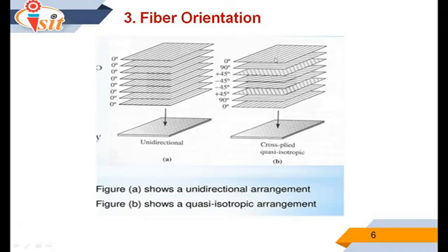In the second picture, at the right side, you can see that in the first plate the fiber angle is at 0-degree. But in the second plate, the fiber angle is changed to 90-degree. Then in the third plate, again it is at 45-degree. In the fourth plate, it is 45, but in the reverse direction. That's why we have written plus minus 45 here. And in the next plate, it is the same, and we have made a symmetrical impression at the bottom side.